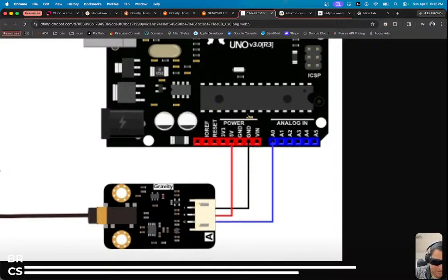Okay, so then blue is whatever pin out, so we're gonna go with D2, assuming D2 is something I have available. And then black is ground, and so I'm gonna hook up black to black on the breadboard. And so black ground from there to here. There we go. Now the whole rail is grounded, supposedly.